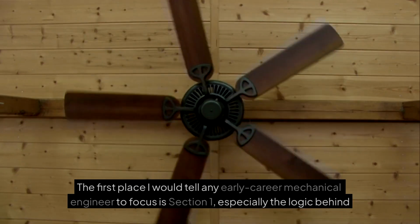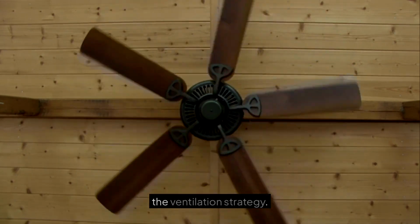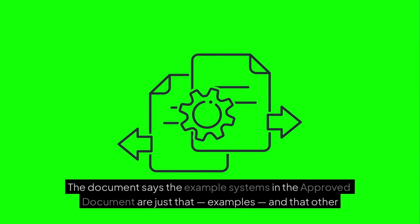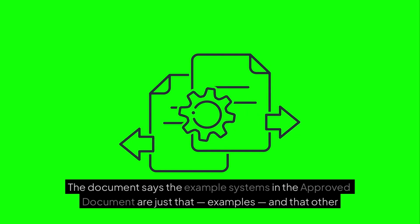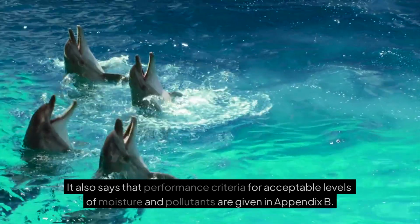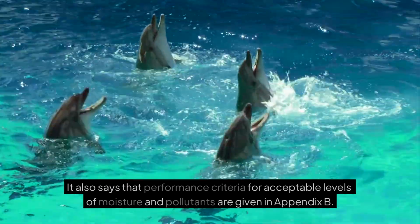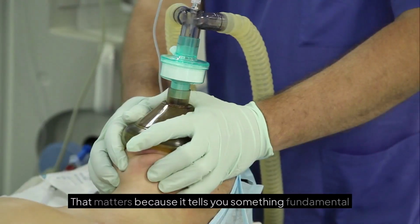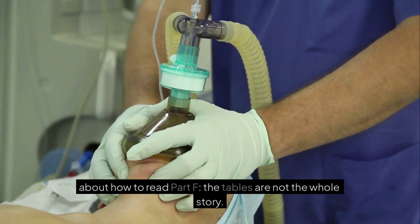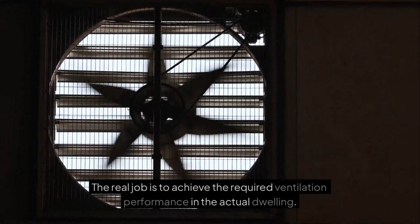The first place I would tell any early career mechanical engineer to focus is Section 1, especially the logic behind the ventilation strategy. The document says the example systems in the approved document are just that, examples, and that other systems may be acceptable if they can be shown to meet an equal level of performance. It also says that performance criteria for acceptable levels of moisture and pollutants are given in Appendix B. That matters because it tells you something fundamental about how to read Part F. The tables are not the whole story. The real job is to achieve the required ventilation performance in the actual dwelling.